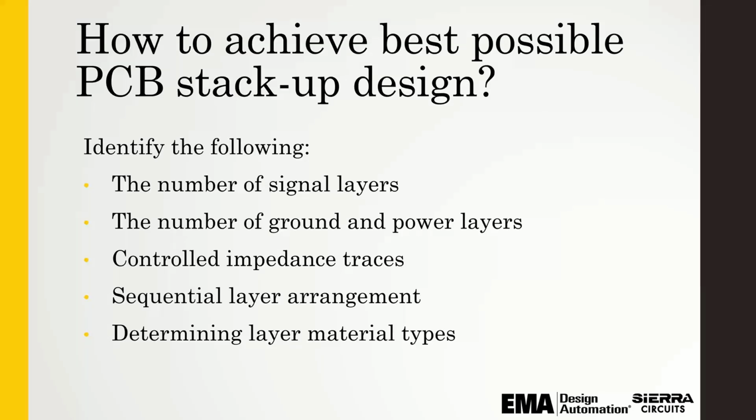Okay, so how do we achieve the best possible PCB stack-up design? Consider what your application is. Whether it's an HDI or standard stack-up, you need to follow certain guidelines that are just best practices. First is understanding how many signal layers and power planes you would need. Your stack-up is truly dependent on the number of signal layers. If you have a lot of high-speed signals or a high-power application, you're going to require more layers compared to lower speed applications. And that's totally okay. It's just the nature of the beast.